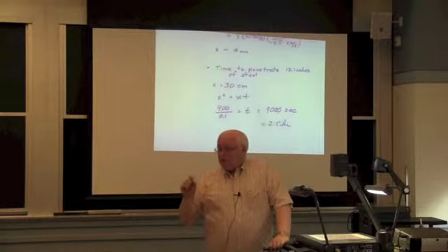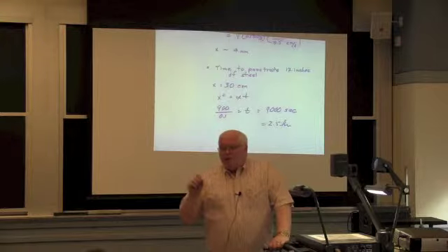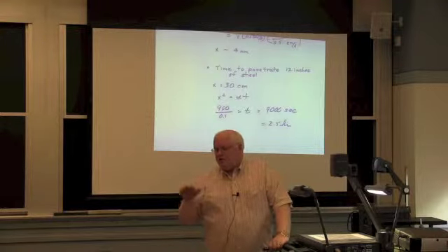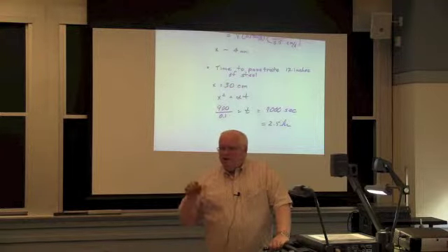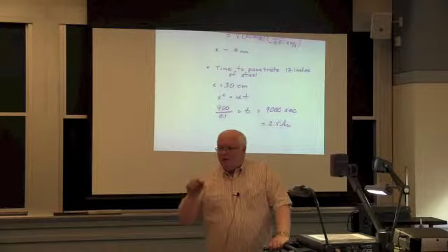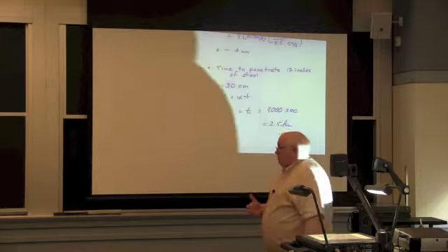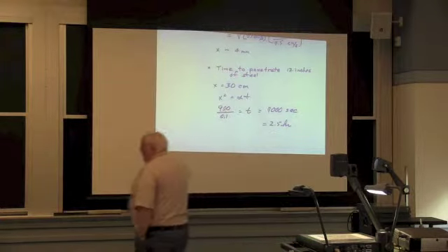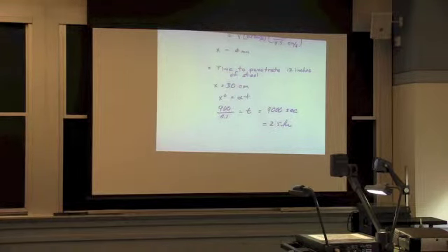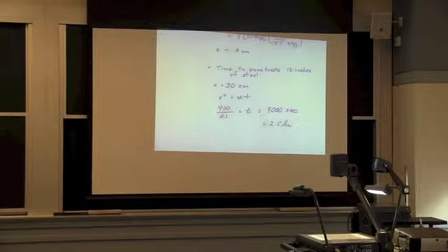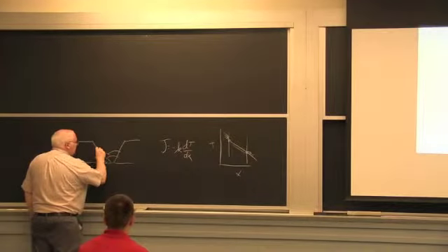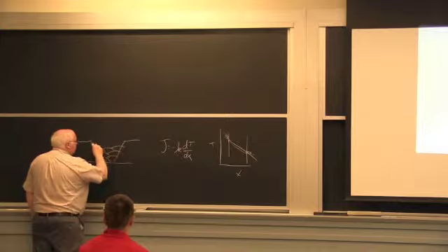There are times when you want to know the size of the heat affected zone. For example, there are certain types of boiler steels where you actually want to use the top pass in a multi-pass weld to temper the bottom pass. We call it temper bead welding. So I'm going to make some heavy section joint in some pressure vessel, let's just call it a chrome moly steel.